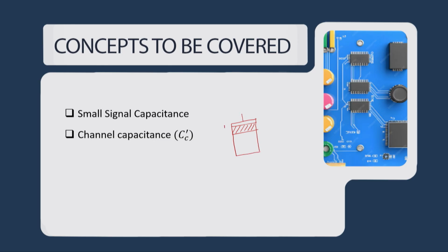This structure, which is called MOS, acts as a parallel plate capacitor when we connect a battery or an external voltage between its gate and body terminal. It is more than a parallel plate capacitor because the other plate of the capacitor is replaced by a semiconductor. Instead of a metal plate, we replaced it by a semiconductor, and the semiconductor does have charges.